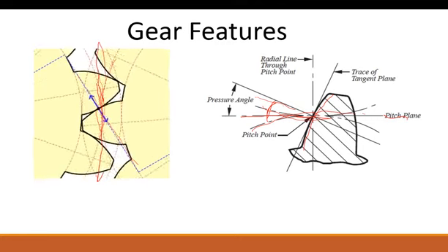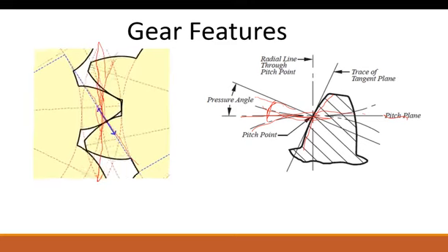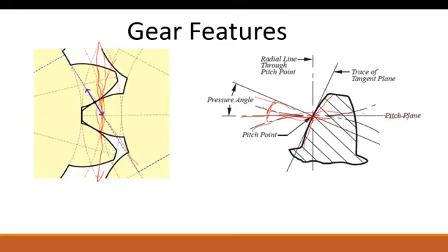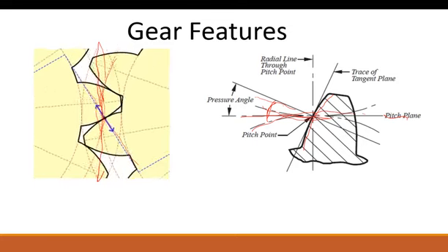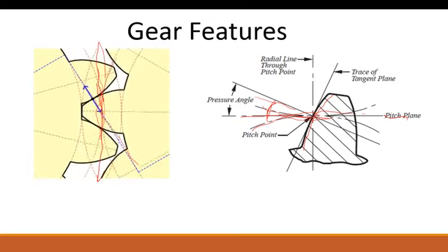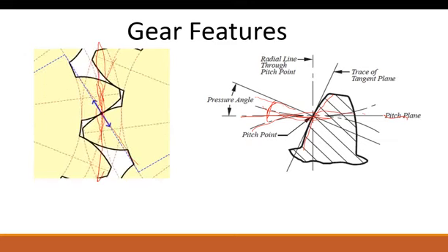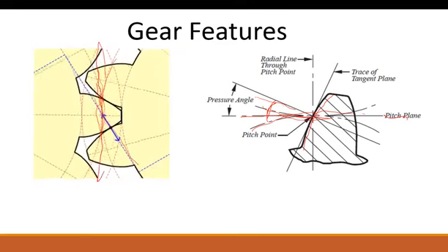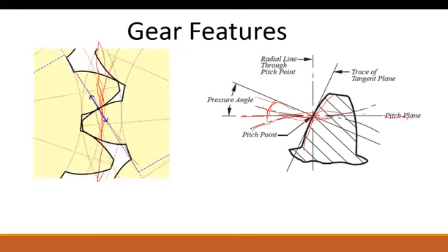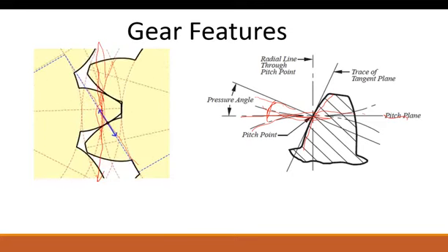So this is how the gear geometries and the gear features, from the last schematic, actually lay out. And this picture over on the left is just giving you a visual as to how these things actually interact in real life. And you can see the benefit of that involute. If these didn't have that involute shape, it would be a much more jumpy, much more abrupt transmission of power between the two. We'll get into more on that, but just keep this in mind as we move forward.